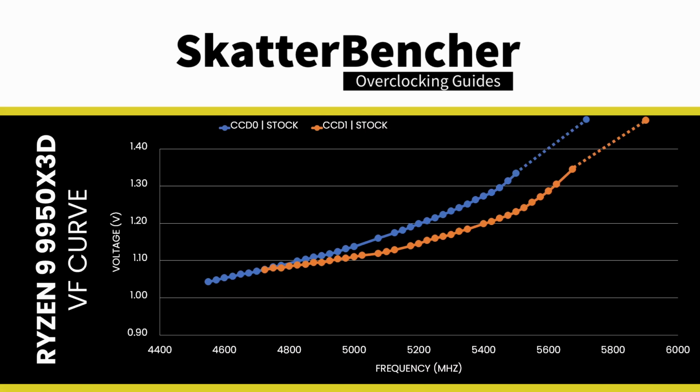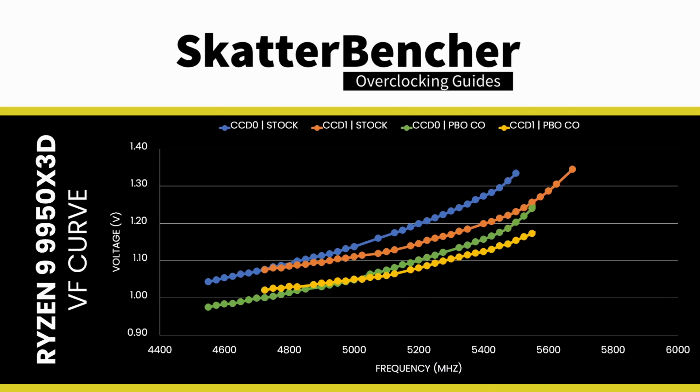So even though we have a higher frequency ceiling, because the frequency points are above the 1.35 volt threshold, we won't see those frequency boosts in all core workloads, however light they may be. If we set a negative curve optimizer, we can shift the entire voltage frequency curve along the voltage axis, and suddenly we need a lot less voltage for every operating frequency.